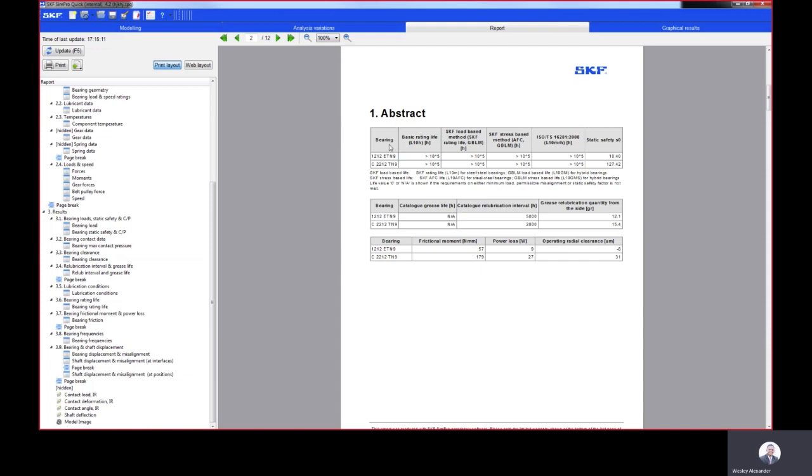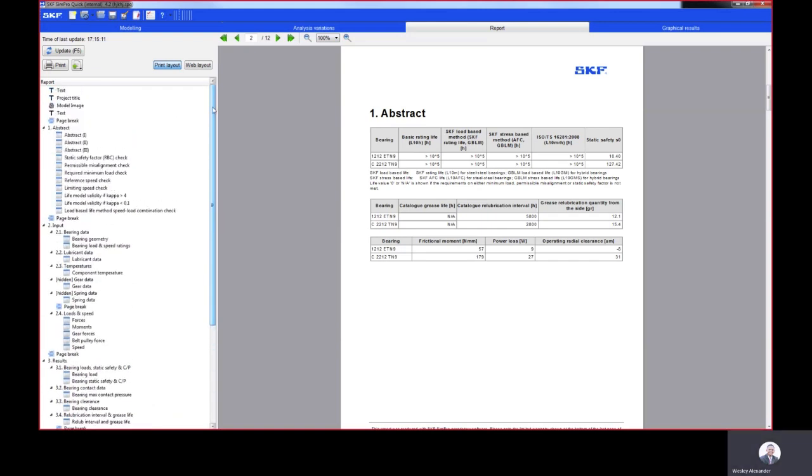So your basic bearing life is your L10 bearing life. Your SKF load-based bearing life also takes into consideration lubrication and temperature, as well as contamination. It's worth mentioning at this point that bearing life is only really reliable for a kappa ratio between 0.1 and 4. Anything outside of that, really, the results cannot be relied on. Well, it's not perfectly accurate for that anyway.